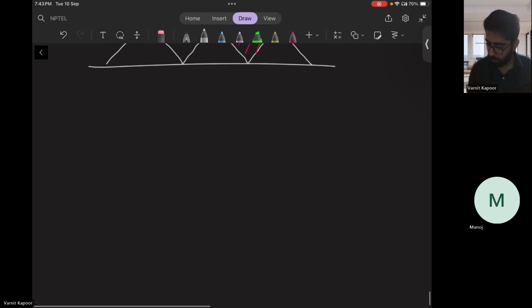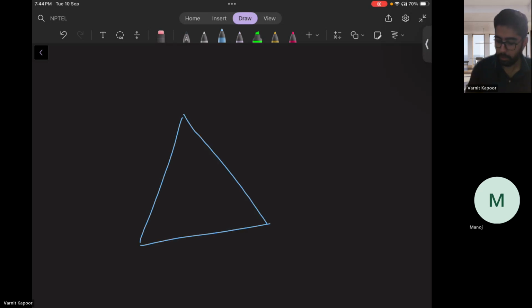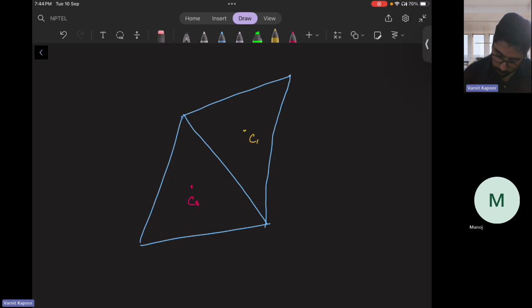Okay. So let me draw the mesh. Suppose this is your cell C0 with cell centroid, and this is your cell centroid C1. The line joining C0 to C1 is this, and the area vector is here, parallel. Let us assume that this is your zeta coordinate, e zeta hat, and this is the local coordinate, e eta.